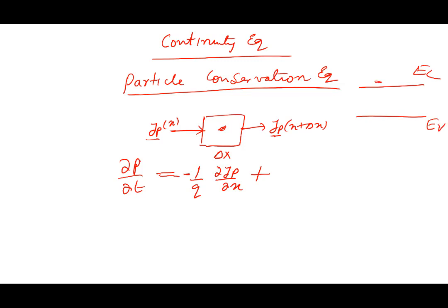Through a thermal generation process. The electrons from here went here, and you ended up with an electron and a hole. There is a generation process always going on. And on top of that, you can have light and other things. So we need to add a generation rate of holes, which we call GP. And then if this is happening, a reverse process is also happening, which we call recombination.